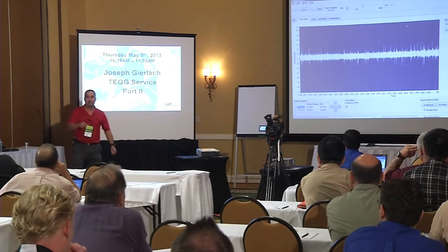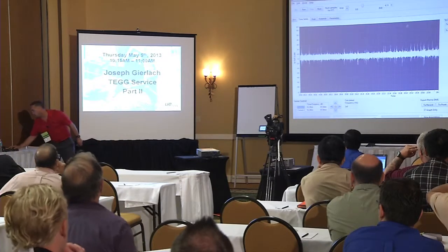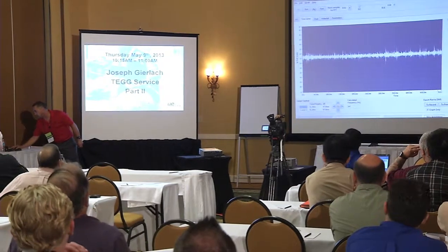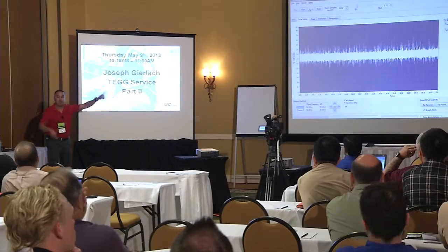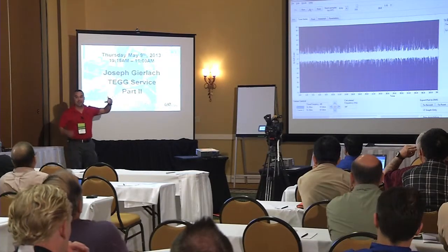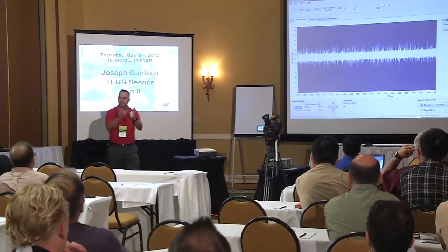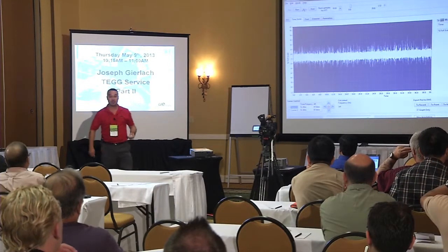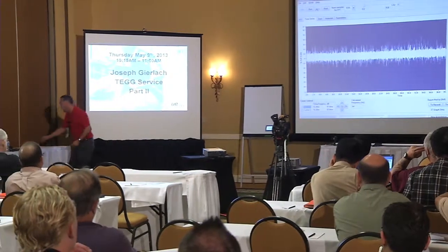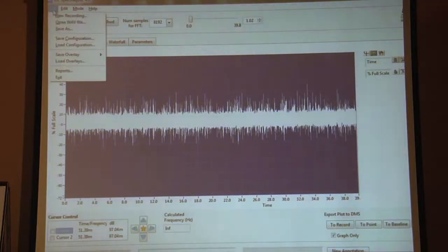We don't have periods through this recording where it is completely and totally silent, do we? Through the entire length, we have these discharges. So we know there's no periods of silence. That rules out arcing. But the fact is, when we magnify in and take a slice in time, we can see differences in both the intensity of the discharges and the timing. That, ladies and gentlemen, is tracking. And it was. It was on the insulator on the switch leg. The second one, with all the popping, is even more revealing.